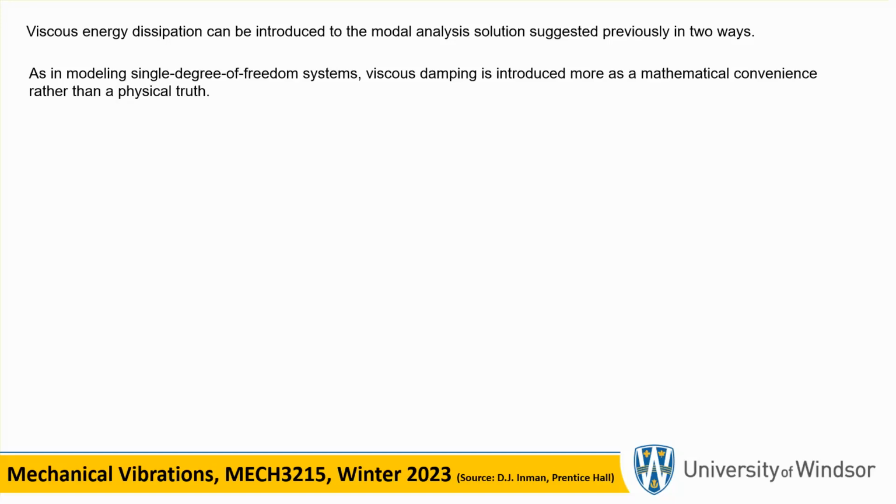On the other hand, if there are other types of damping that are involved, for example, frictional damping, or what we refer to as Coulomb damping, the equation becomes nonlinear if you try to incorporate that directly.